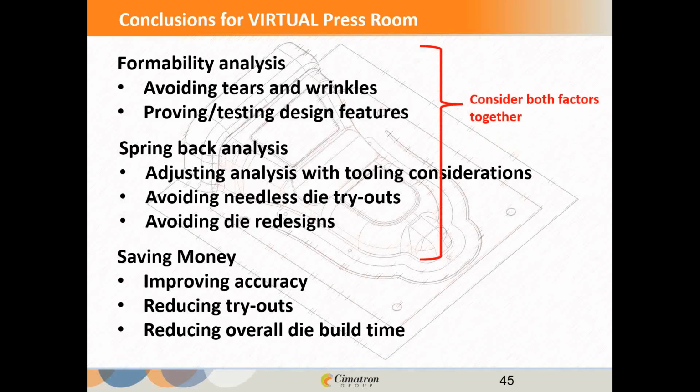I hope I've illustrated to you how one little addition in your design thinking, one addition like a draw bead, moving a pilot hole, can affect the overall outcome to your advantage or your disadvantage. But being able to prove it on the screen, here you've got something that you can sit down together with and look at and say, this is the best way to go about tackling the job because we've considered this, we've considered that, and this is predictively what is going to be the best solution for our first tryout. Will it take away all die tryouts? Well, can't say that, but why not take away those that are the needless ones?